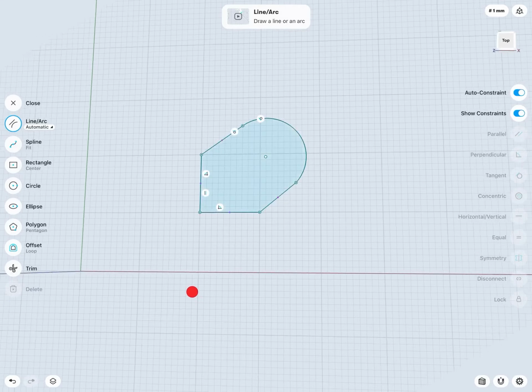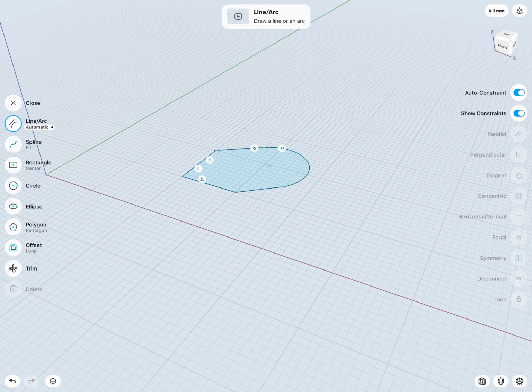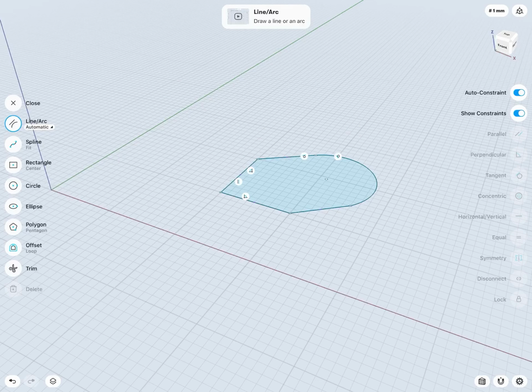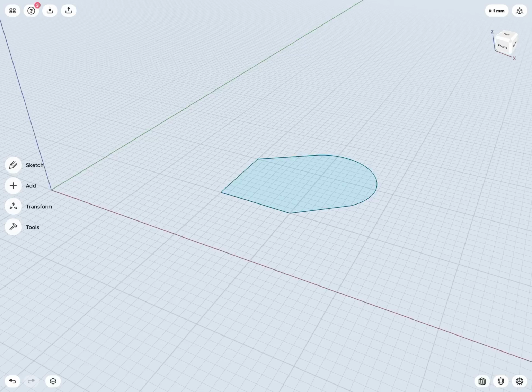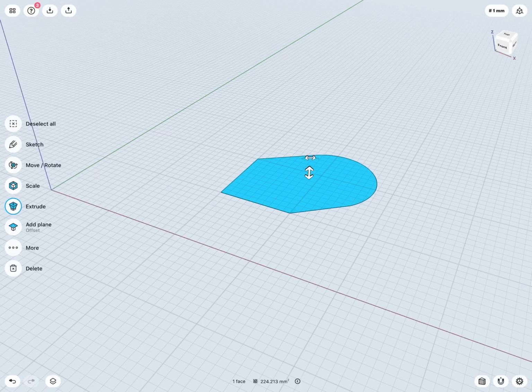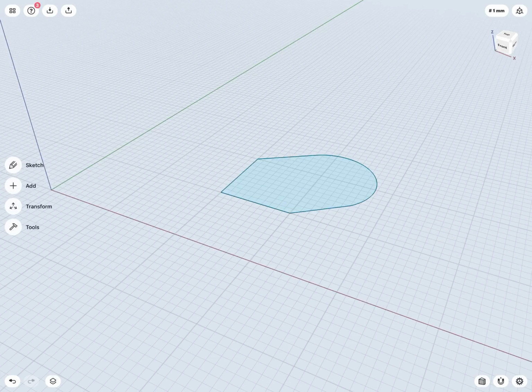Also notice as I go into a bit of a 3D view, that sketch is coming in as a light blue color. And that's useful. It's just telling me that this is a closed out sketch, meaning that eventually we might be able to create a 3D object from this sketch by using our extrusion or other 3D tools, and we're going to learn more about those later on. In the next few lessons, we're going to learn more about sketching splines, as well as using constraints and dimensions.